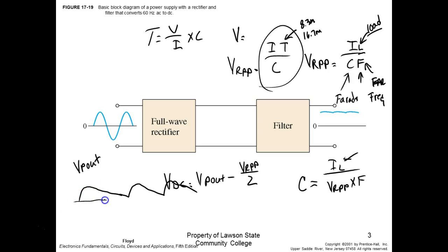And if we calculate our capacitor right, all we're trying to do is get an idea of what the current might be, right? We know it's going to be lower. So normally our estimation of the current out of the load, all we use is V peak out over R. Now we know it's going to be less than that, right? You understand? But this is close enough for what we call approximations, right? Y'all understand that? So we'll use V peak up there for load current, C and L.